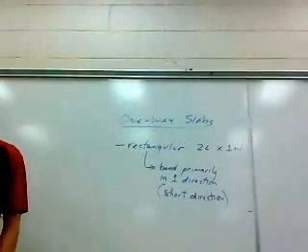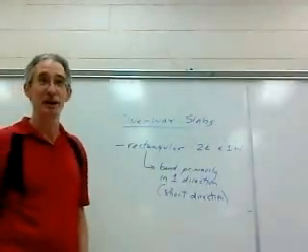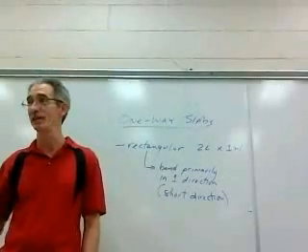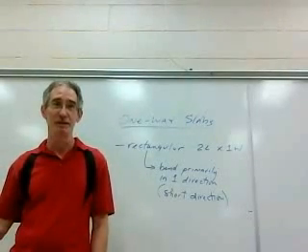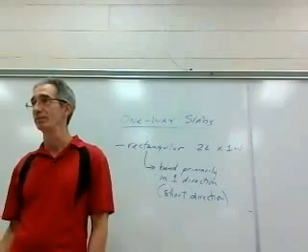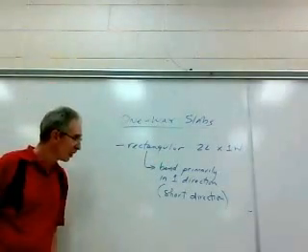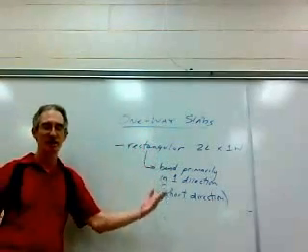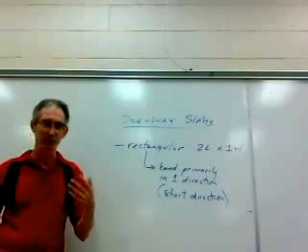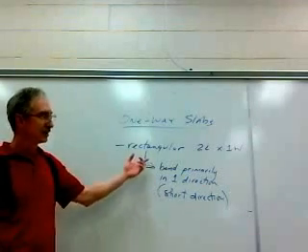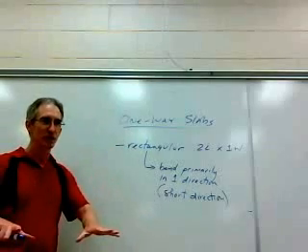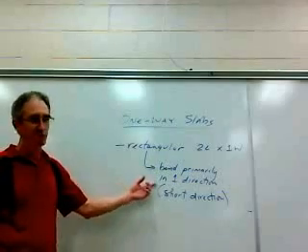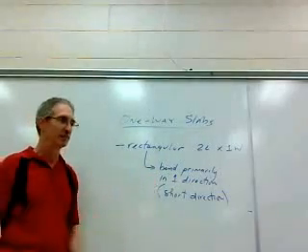Everything that we've talked about up to now, phi Mn greater than or equal to Mu, phi Mn equals phi times T times the quantity d minus a over 2, all that stuff still holds true for one-way slabs. Okay? So a one-way slab is a rectangular slab. Again, in reality, this will be monolithically cast, just like we talked about the beams and columns being all monolithically cast. Being rectangular, and you put floor loads on a rectangular section of slab that's rectangularly supported, it'll bend in the short direction.